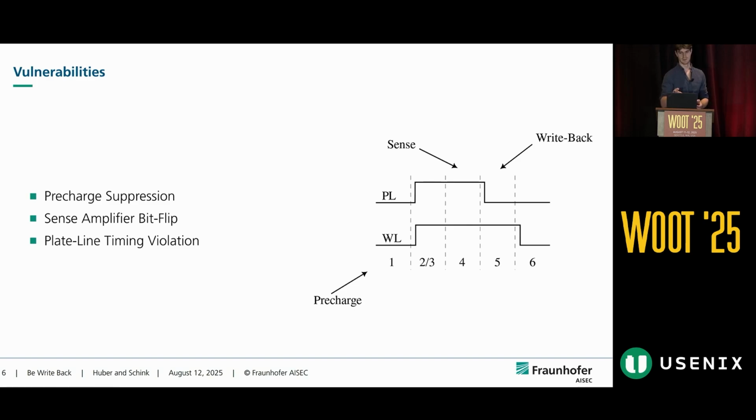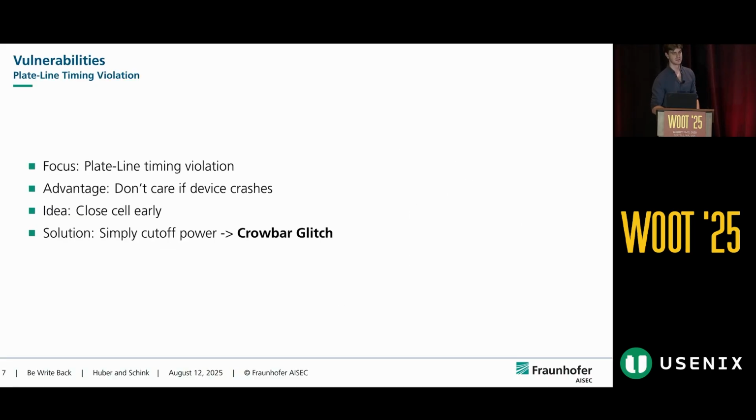If there's a mismatch between the plate line timing and the word line timing in the write-back step, then this will leave the memory cell in an undefined state where both crystals are polarized in the same direction. And this is also the vulnerability where we focused.